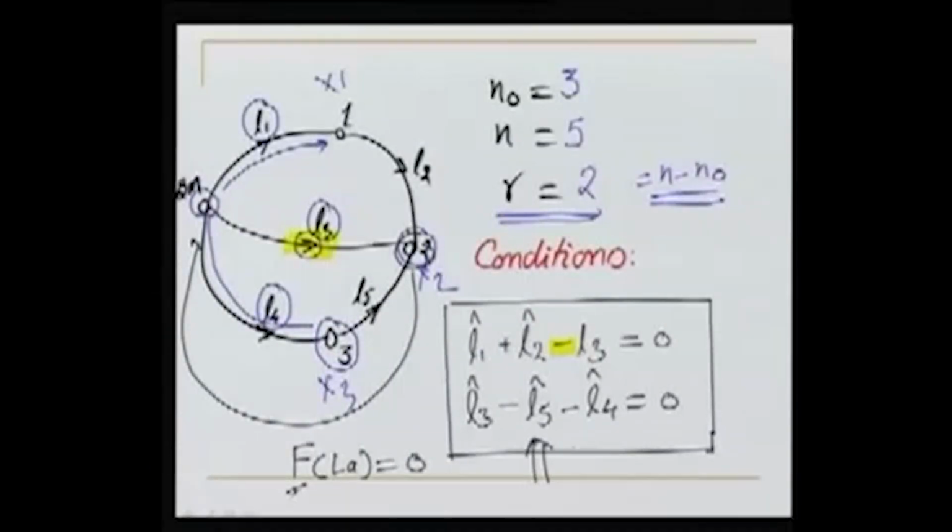It's a function of the adjusted observations, the estimates. That's why we are using L hat here. And the relationship between adjusted observations, whatever all the possible relations which are there and which are independent, we write them in this form. So these are the condition equations. Later on, we'll make use of these condition equations in order to find the solution by least square.